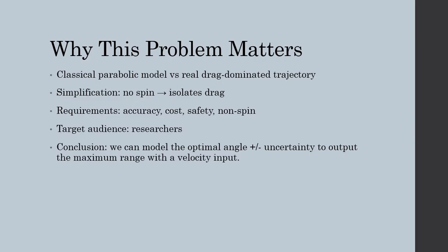The flight path model was generated through experimentation. A golf ball was launched from a pneumatic air cannon at various angles, and the launch velocity and projectile range were measured with the appropriate instruments. The golf ball was encased in a 3D printed sabot to prevent the ball from spinning. Using the results, the team created a model relating launch angle to the expected range. The resulting model has an associated uncertainty that is within the plus or minus 10% margin of error specified by the client. This accuracy makes the model suitable for the customer's intended use.